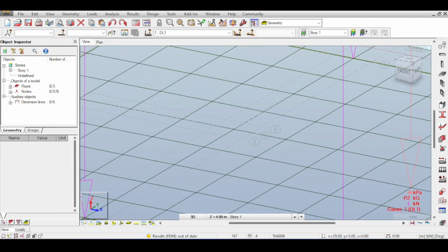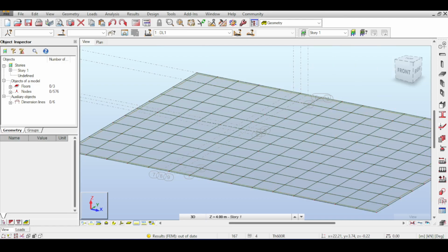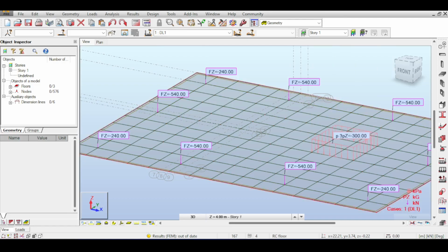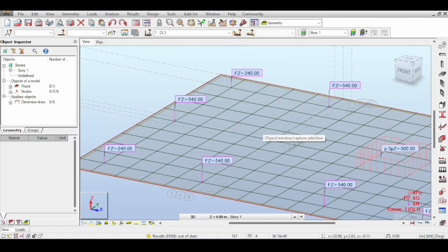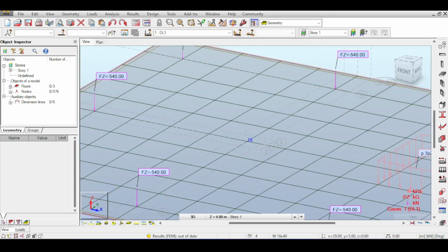This is my column now, and this time my column is actually not ridiculously big like this. This time we're going to enjoy having a real column, because we should make sense of this stuff. Fine, this is big, I'll just keep it for the sake of showing you this. So for now, I will do the same thing, but this time I remember that the area, and I have my calculator right beside me, is 0.7 multiplied by 0.7, which is 0.49 meters square. Now the dead load is 1,200, which means if you take 1,200 divided by 0.49, the pressure here is going to be a whopping